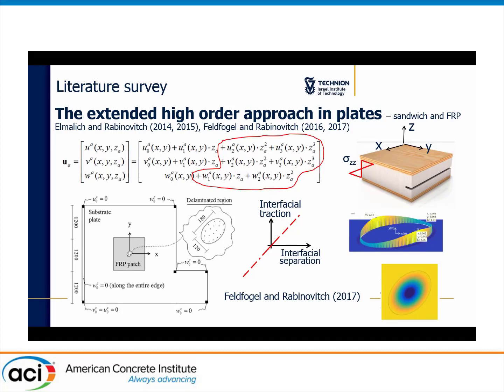We see that on top of the displacement terms that designate the standard plate theories, this, for example, represents a plate theory with first-order shear deformations, these are the terms of the enriched displacement field, which corresponds to the high-order modeling, and which gives rise, for example, to this linear variation of the sigma ZZ in the soft layer.